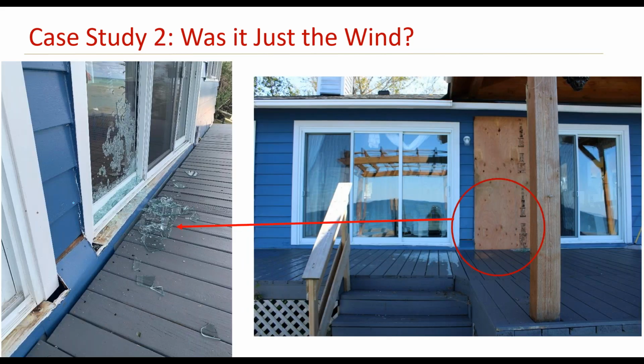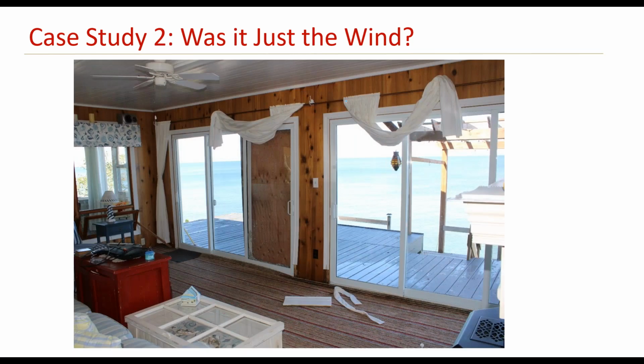When we got a closer look at the exterior wall, we noticed that there is dislocation of the wall, a couple of inches, especially at the location where there is a structural support almost midway through the wall. We also noticed we have shattered glass. So again, everything is in agreement with structural damage due to severe wind. We get into the building, with the finishes intact, still in place, nothing out of the ordinary.